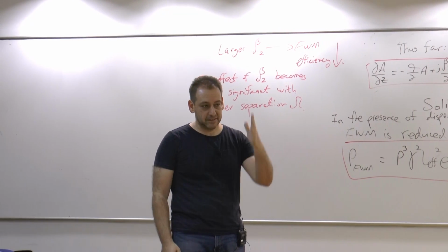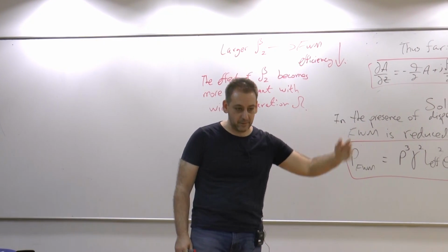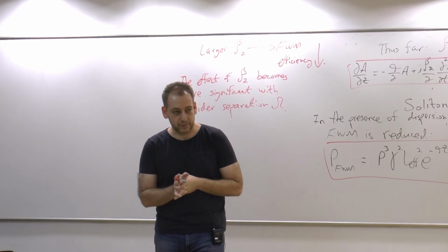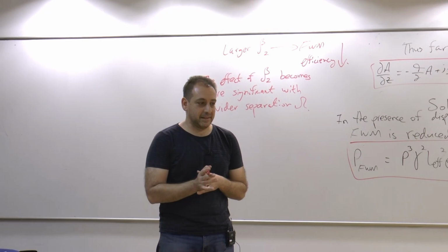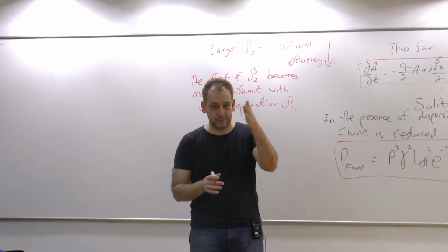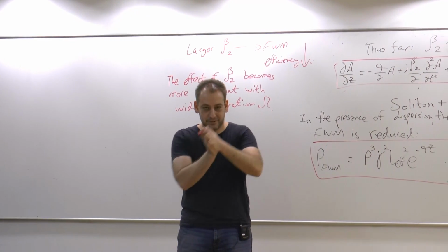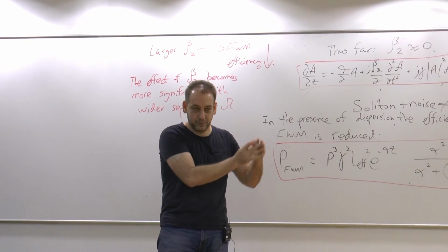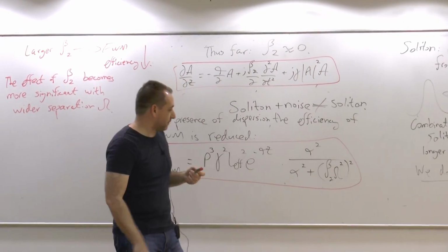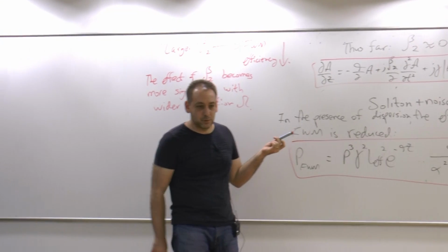We are launching channels 1 and 2 and 3 and 4, and we rely on separation between these channels to relay information, and we are making huge efforts to guarantee that there are no leaks, that information from channel 1 does not appear in channel 2 or 3 and 4, because if it does, it's impossible to separate them. But this is exactly what four-wave mixing does.